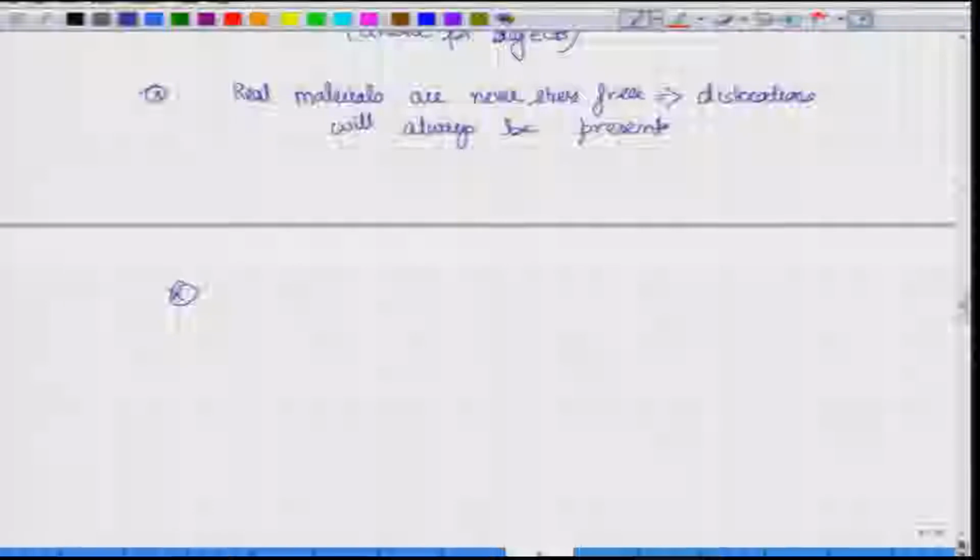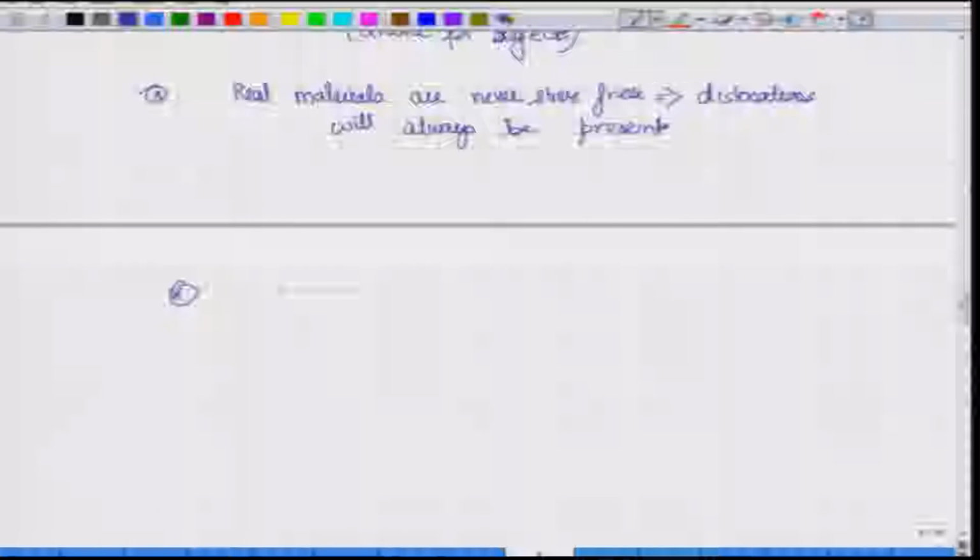Depending on the stress, you will get different amounts of dislocation density, but on average, for a metal or an alloy system, there is an approximate range. And what is that range? In an annealed material, approximately 10 to the power 10 per meter square. And why do we write the unit per meter square? If you remember from part 1, it is meter per meter cube, and therefore it becomes per meter square.